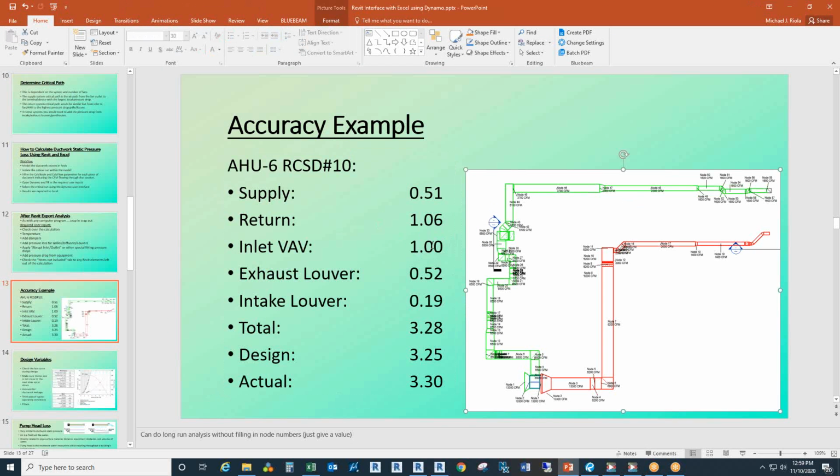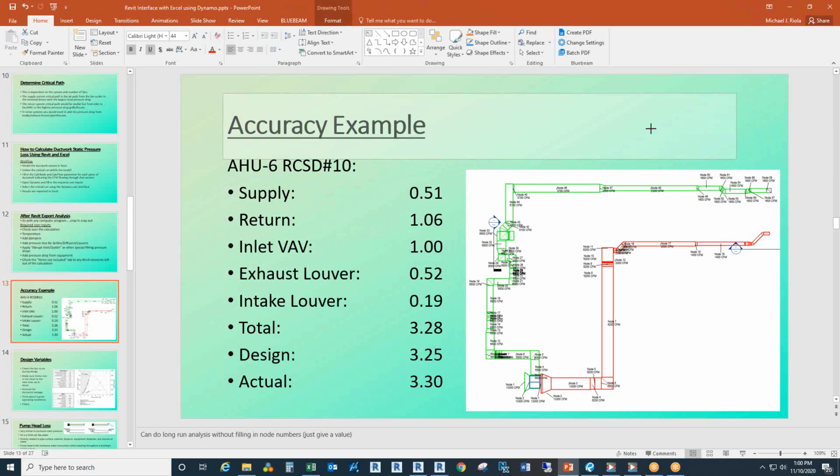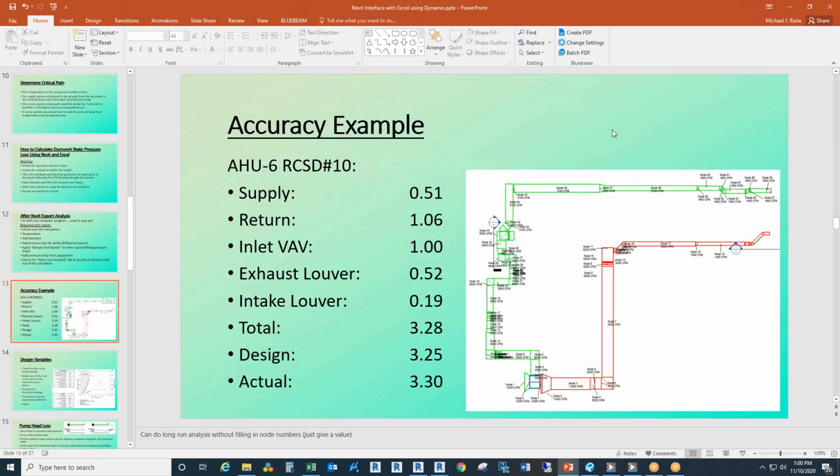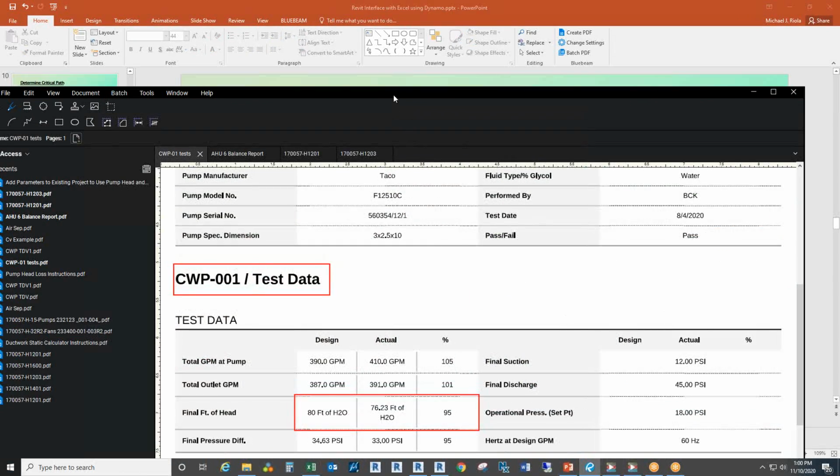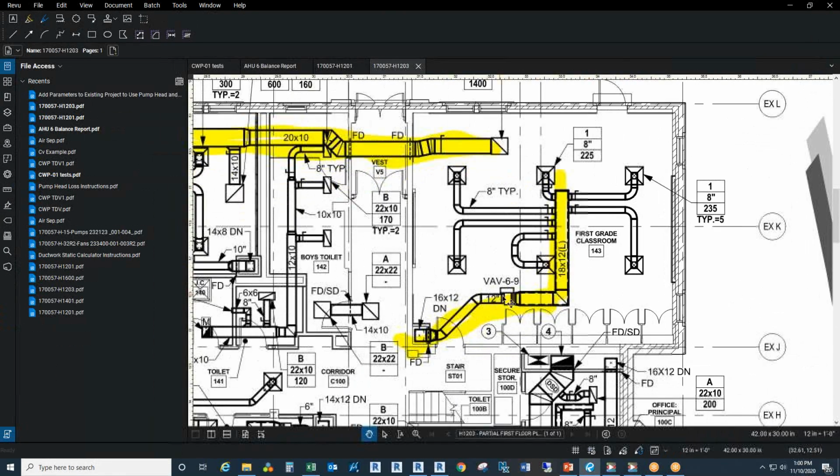No, that's in there, right? So when I selected the VAV, it expects 1 inch of static pressure at the inlet, so it operates as intended with the pressure drop across it. Some VAVs, as far as I'm aware, don't function properly and sense the pressure properly unless they have enough pressure at the inlet. Okay, you're right. But so you're supplying that 0.5, that doesn't include anything downstream of the VAV. That's just up to the inlet. Yeah, it's just up to the inlet. There is ductwork downstream of the VAV here.